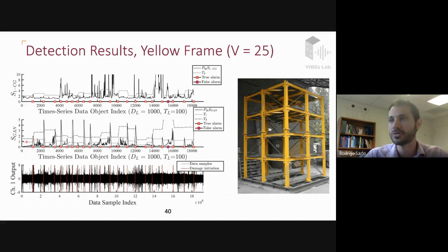And there are two thresholds. The first one is the more aggressive one, and then the top one is the more conservative one. If the score exceeds the conservative one, that's our first detector, and it's immediately flagged as damage. So as you see, these cases were all pretty obvious novelties. Sometimes the novelty is not so obvious. That's when we use the more aggressive threshold. If that's exceeded, then we also check the lower dimensional feature score up here. And if both of those are exceeded, then we flag a damage.